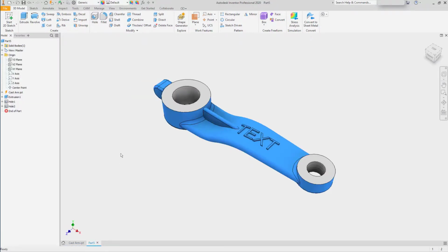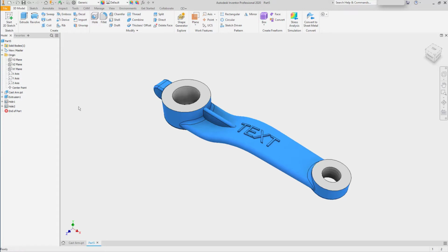Now imagine that there's any number of machined parts derived from the solid. Every time you open one of them, you just simply update the casting that it was based on, and the part is updated. Then, any drawings or any other assemblies that those machined parts are in will also be updated as you edit them.